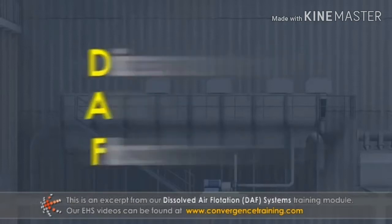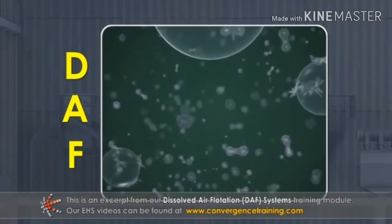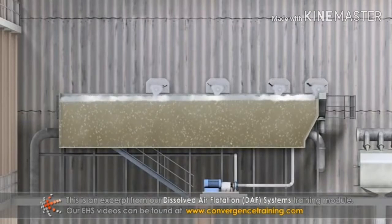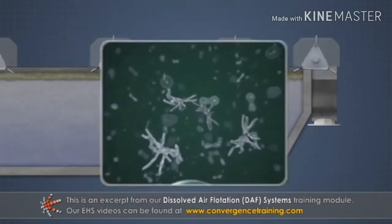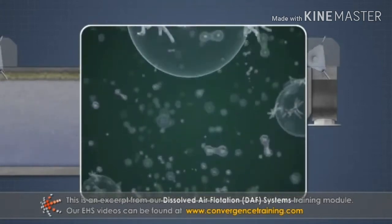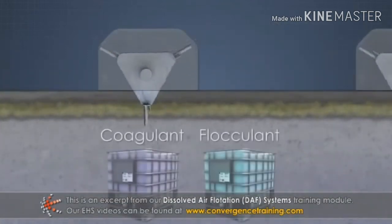Dissolved air flotation, or DAF, is a water treatment process that removes suspended solids from water using air. This separation is achieved by dissolving air into water under pressure and then releasing the air at atmospheric pressure in a flotation tank. The released air forms tiny bubbles which adhere to the suspended solids in the water, causing the solids to float to the surface, where they can be removed by a skimming mechanism.